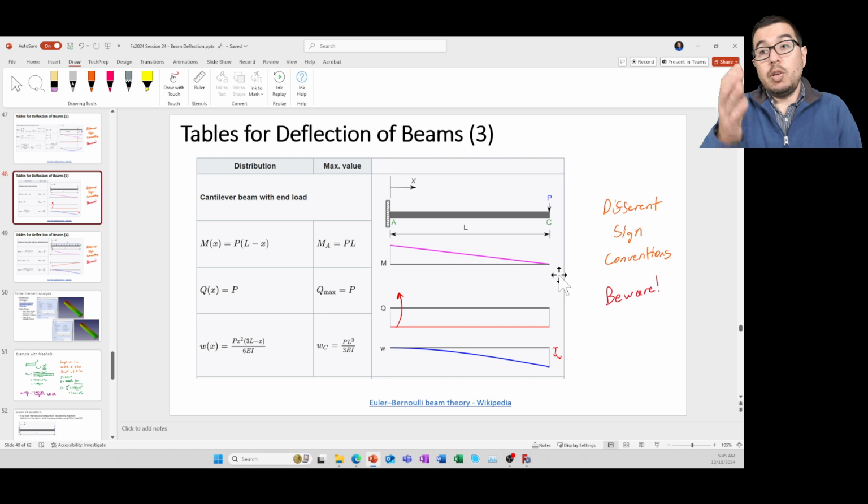Now, there's a dM/dx here, which is equal to the internal shear force, V. So you can have some transverse shear, and you can have some transverse shear stress, especially close to the neutral axis or the longitudinal axis.